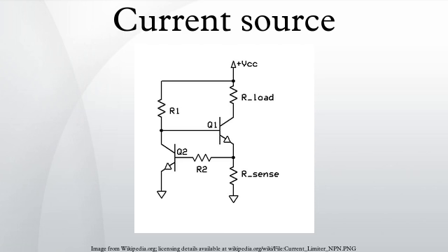Imagine in Figure 5, at power up, that the LED has 1 V across it driving the base of the transistor. At room temperature there is about 0.6 V drop across the VBE junction and hence 0.4 V across the emitter resistor, giving an approximate collector current of 0.4 per R amps. Now imagine that the power dissipation in the transistor causes it to heat up.